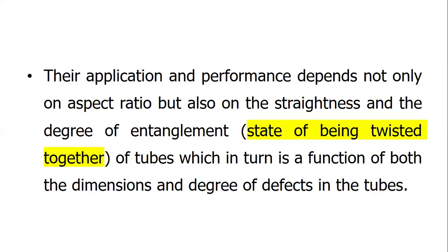Their application and performance depend not only on aspect ratio but also on the straightness and degree of entanglement of the tubes, which in turn is a function of both the dimensions and degree of defects in the tubes.